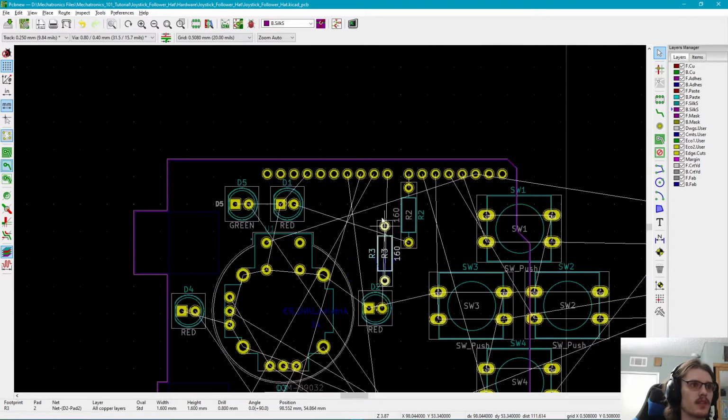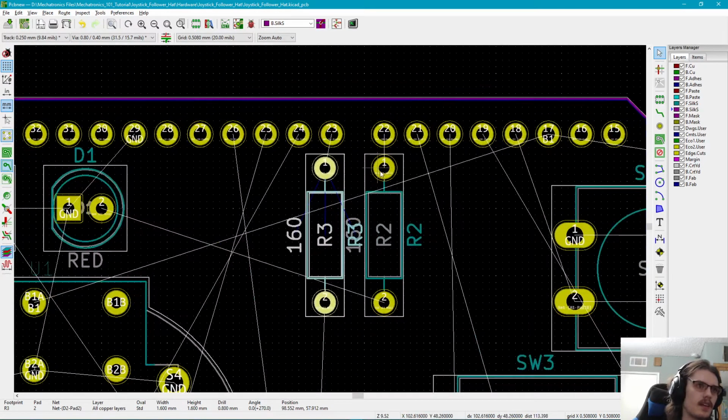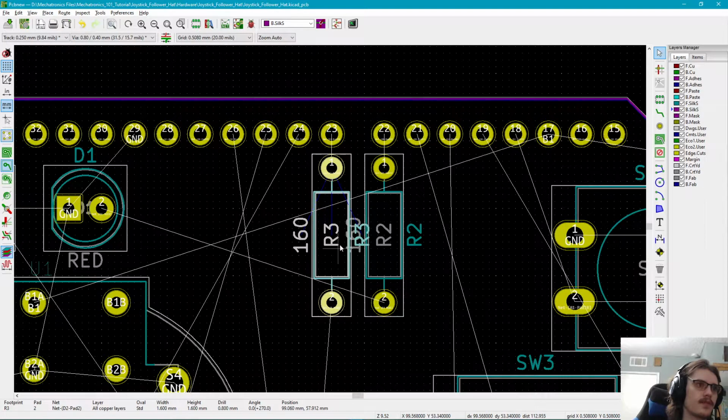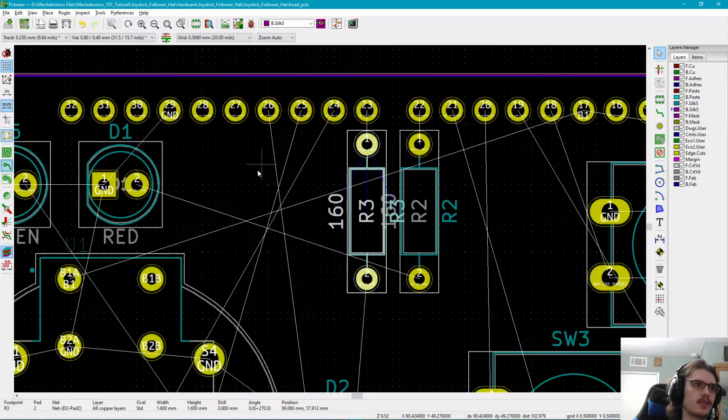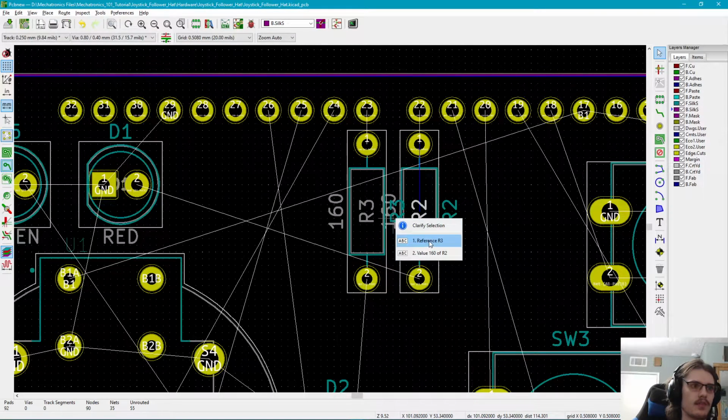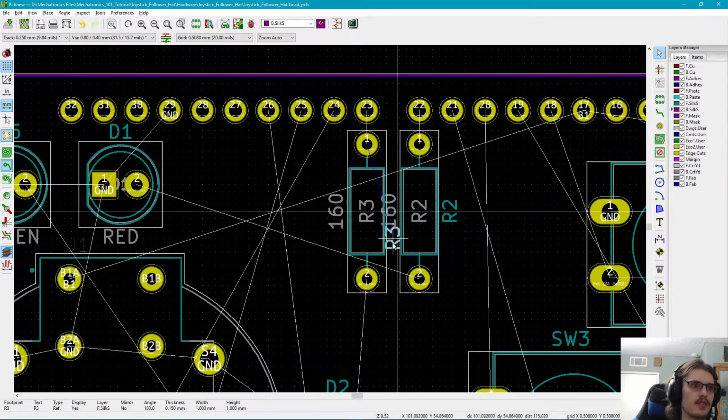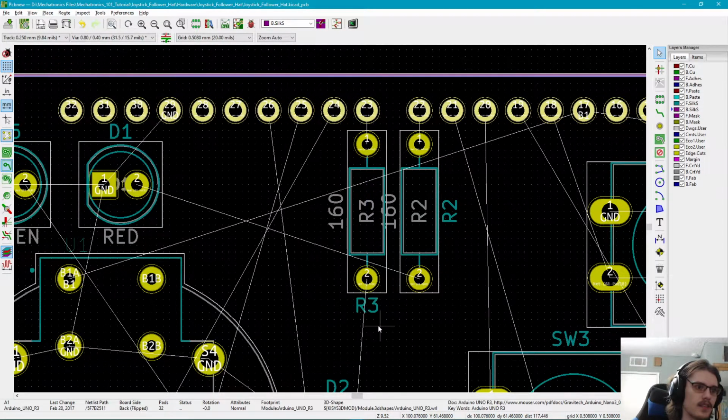So this one is going to connect right here. Now it's going to be kind of tight. We're going to have some overlapping like this. So if we want these resistors to be exactly next to each other, what we can do is select just the reference and move it down, because remember the turquoise will be printed onto the silkscreen.